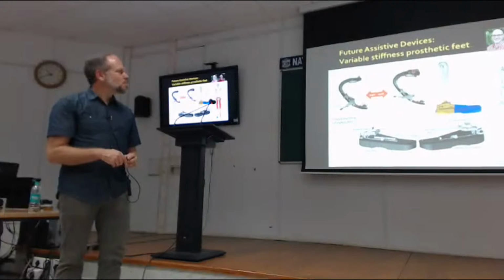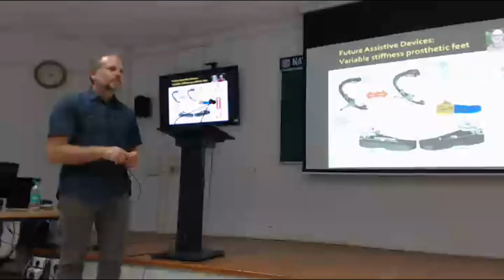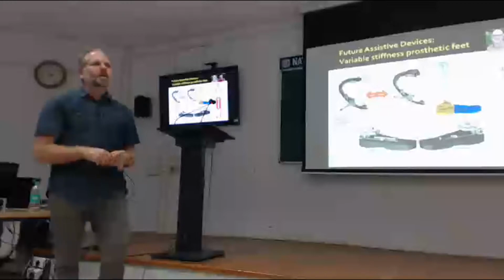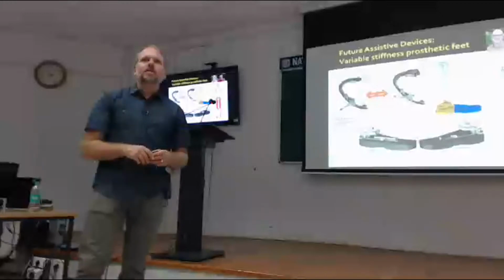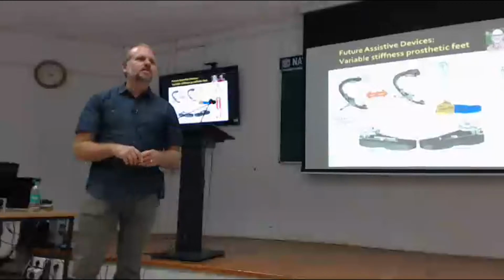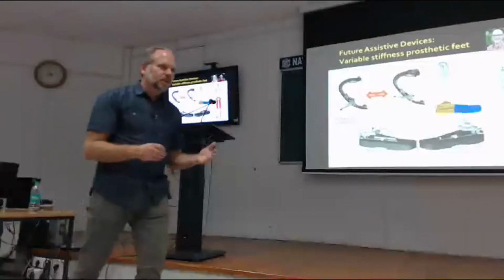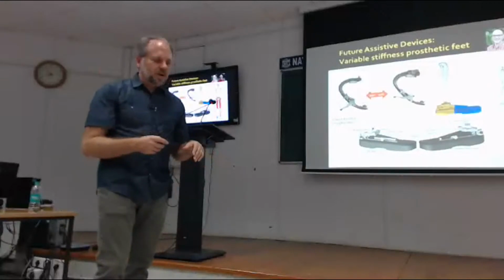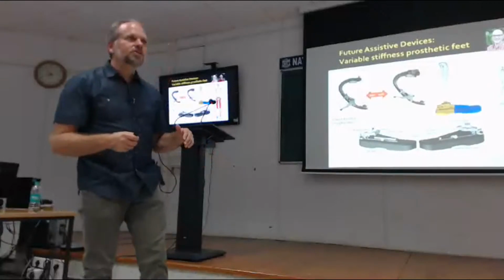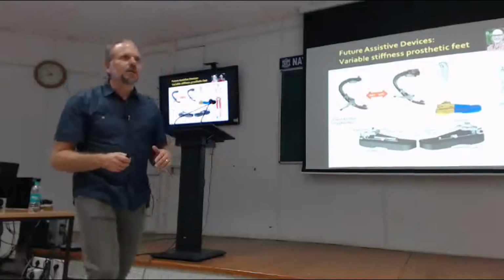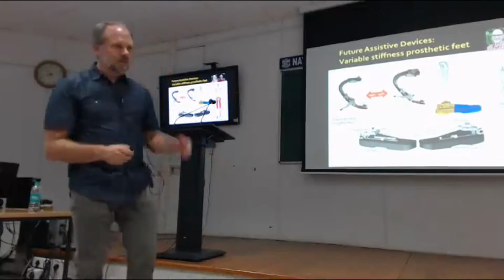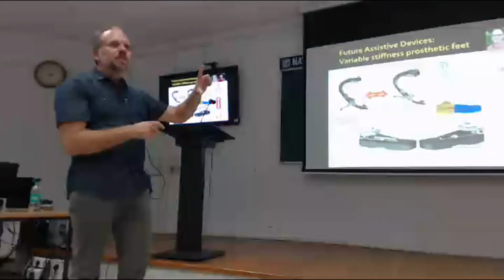The previous one, the bionic foot, does it do things like backward walking? You can do backward walking. It's not the same as what you do with your anatomical ankle, to allow the tibia to roll over the top for a little bit of dorsiflexion. But if I step backwards, it's not going to allow me to change my dorsiflex position before stepping down. So it'll be a 90-degree object that you'd be stepping back onto. So it might be very awkward to force your knee into a hyperextension, but it is possible to do it still.